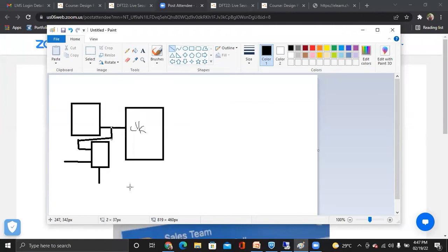Okay. So this is the way we are connecting now. What are we doing? Whatever clock connection is there, we are bypassing using the mux. So this is the top level clock port, which we have defined as a scan port. And then this is the test mode port.